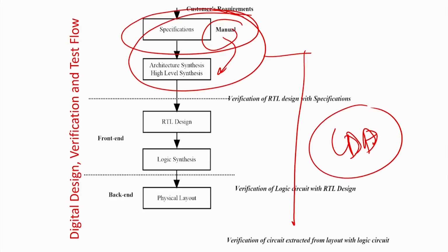Actually, if you look at any standard CAD for VLSI course, there are a lot of known algorithms like Espresso, which solves Boolean function optimization in a very short amount of time. Of course, the optimization quality may not be exactly as good as exact methods, meaning that Espresso is a heuristic. The difference between a heuristic and an exact algorithm like Quine-McCluskey or a Karnaugh map is that with an exact algorithm you will always get the minimum size circuit or minimal implementation.